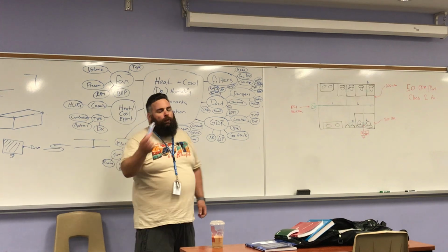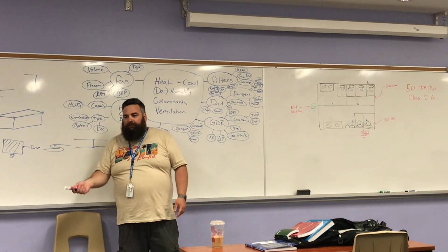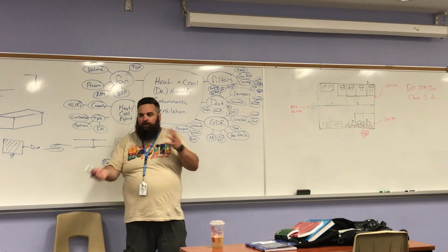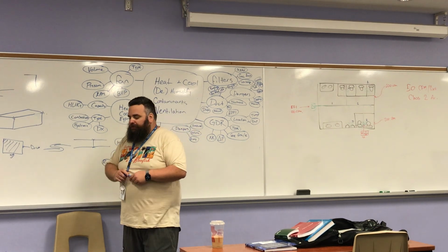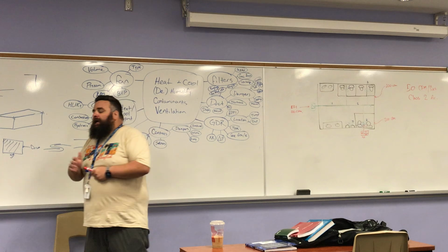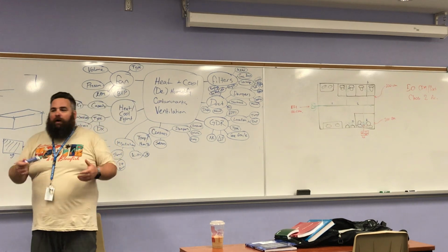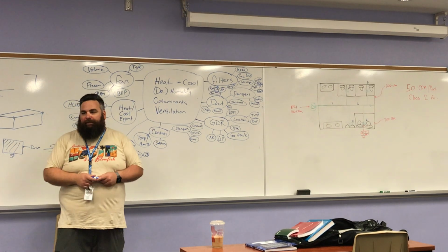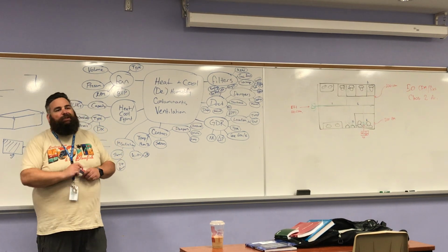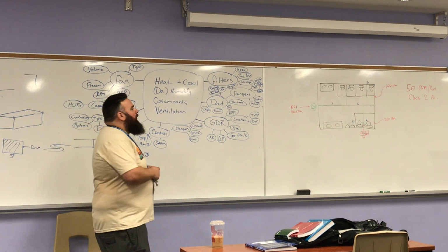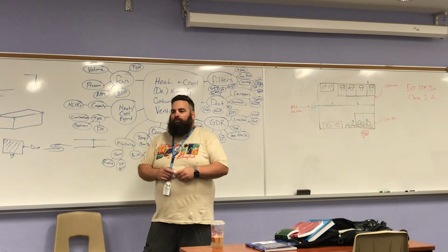Remember how I told you with total pressure, we can trade off dynamic pressure for static pressure? I'll give you some literature to read about static regain. It's not used for supply and exhaust and return. You only use it for supply. You'll see that typically done on high velocity systems, so we're not going to get into static regain. And then there's also constant volume, which we're not going to get into.